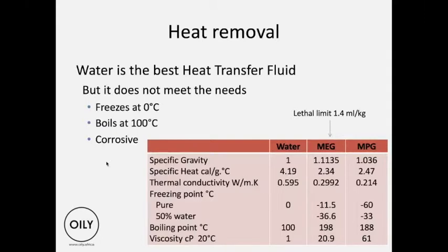So you need something to add to water, that's your coolant additive, so that the water doesn't freeze at 0, doesn't boil at 100, and is no longer corrosive. It doesn't cause rust. That's what we call antifreeze. It's just a coolant additive. Those are the major functions: prevent rusting, prevent freezing, prevent boiling, or rather lower the freezing point and raise the boiling point.